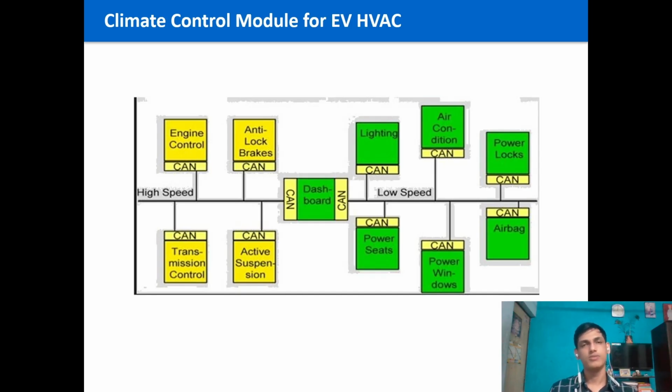All these systems need to be integrated into one, and this can be a little messy. So CAN protocol simplifies it. It just requires two wires, CAN high and CAN low, and it can connect each and every ECU with each other so they can communicate easily. This protocol has a lot more to it, but this is just the basics that I've explained.